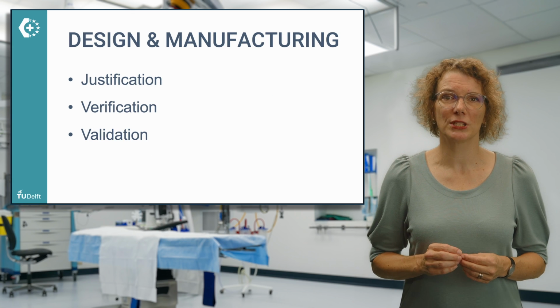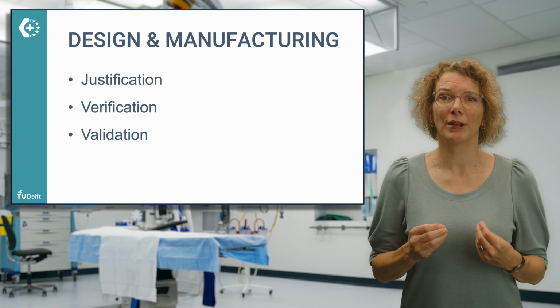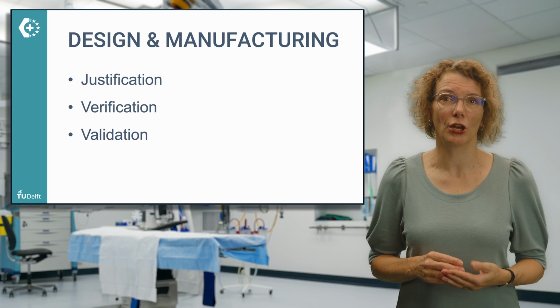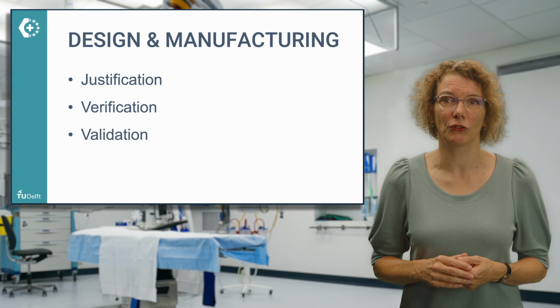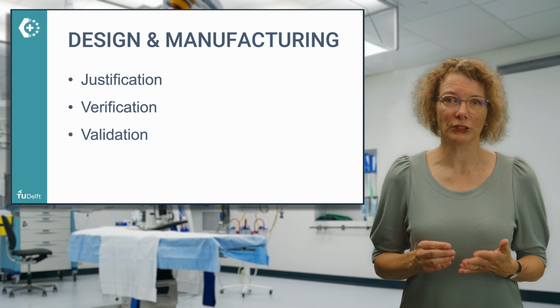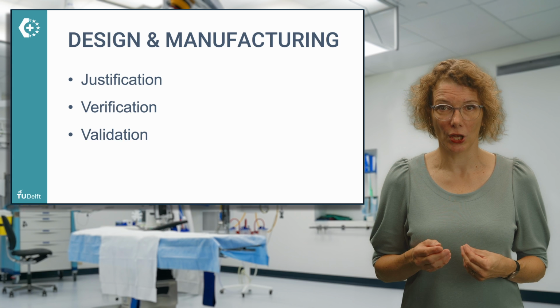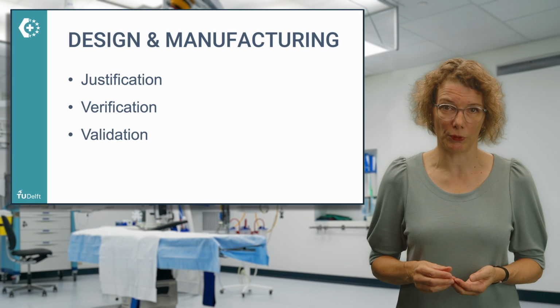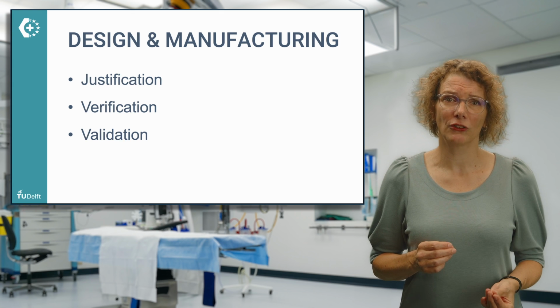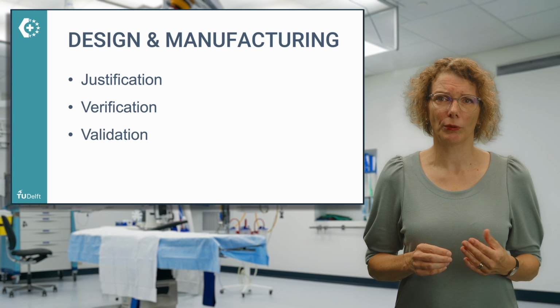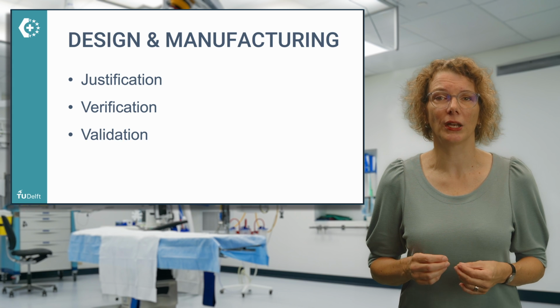To demonstrate conformity with the medical device regulations, a manufacturer needs to provide information on justification, verification, and validation of the design decisions for the device. Justification involves providing evidence of the design stages that the device went through and explaining changes made to its design from one design stage to the next. Such a report is often referred to as a design history file.